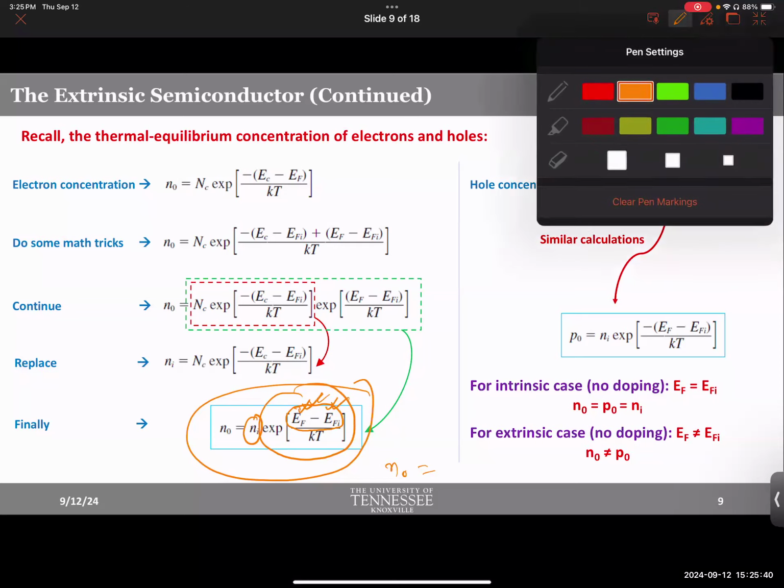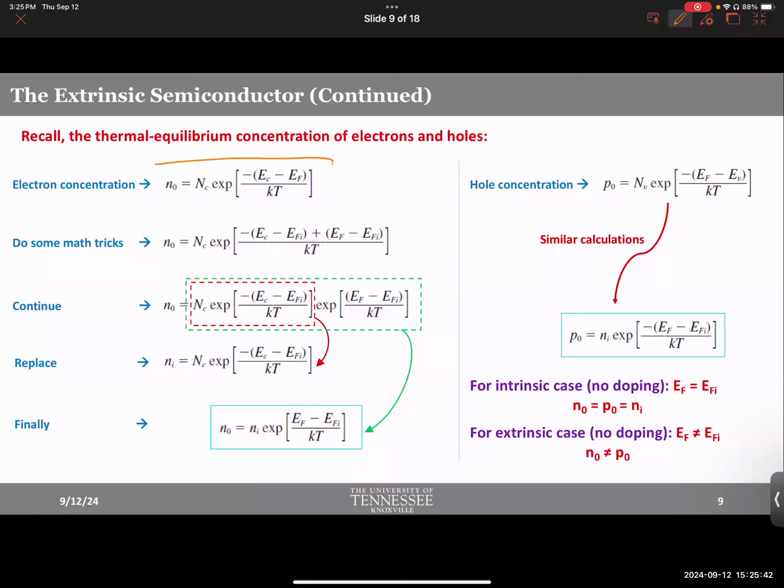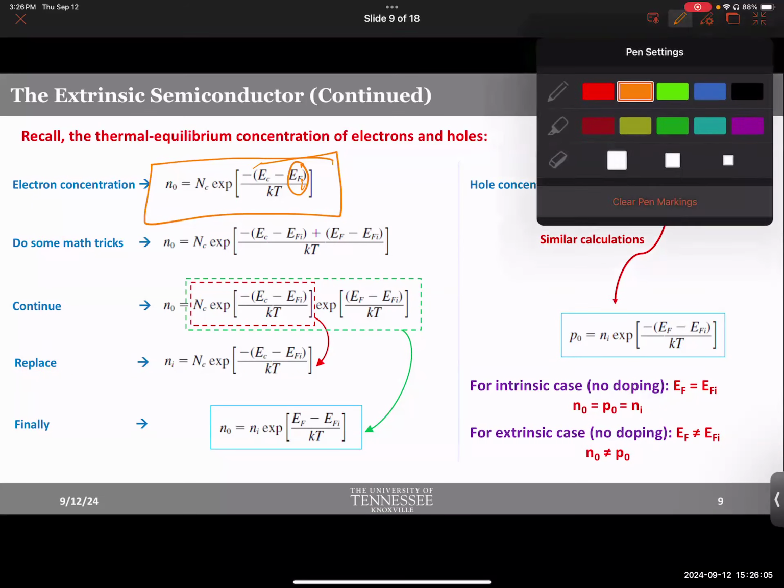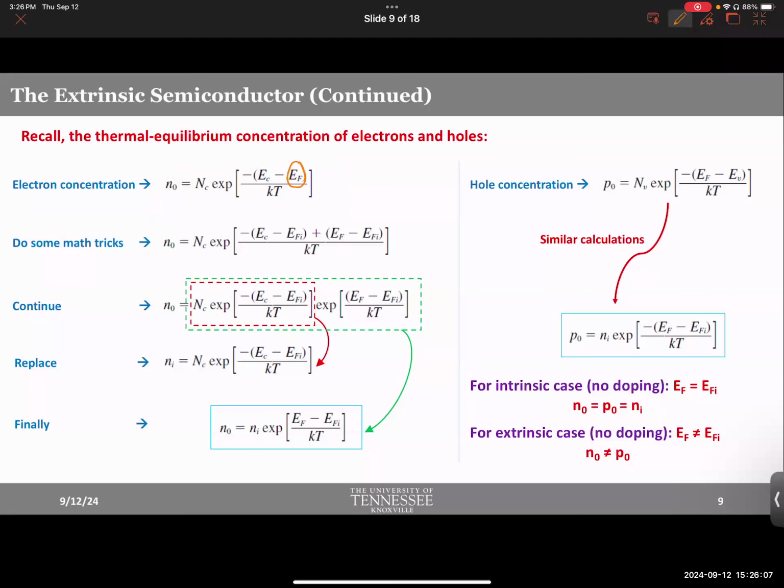Notice that? By the way, I forgot to mention one thing here. What changed in the equation? This equation is basically the same as before. There is just one change. I really wish I could have asked and made you respond. But apparently in the previous lecture, we used to use I, which was intrinsic, because all the Fermi levels before were all intrinsic. We didn't even care about the extrinsic equation there. But now we will have to mention the actual Fermi level, not the intrinsic, because the material is not intrinsic. It is extrinsic now. So that's the only thing that changed.